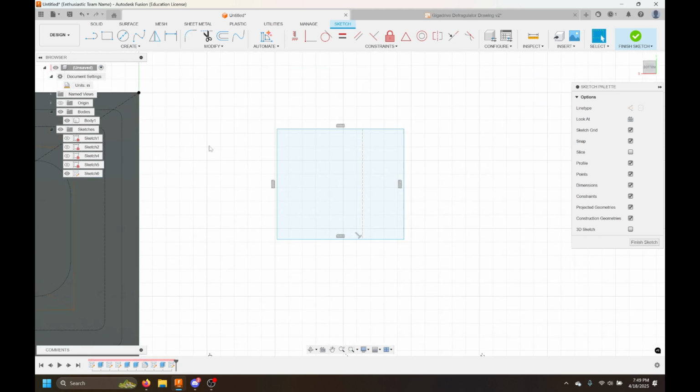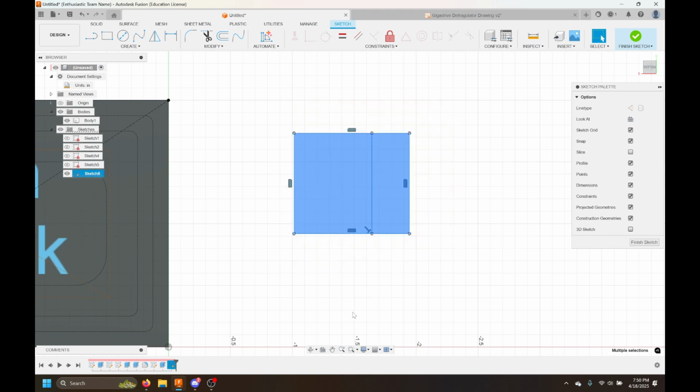If I select right, it will only select anything that is completely inside my selection box. It's very conservative about selection. If I go left, it'll do anything that's even touched by the selection box. So if you're ever trying to select something little and you accidentally do the whole piece, you go the other way. Lovely.